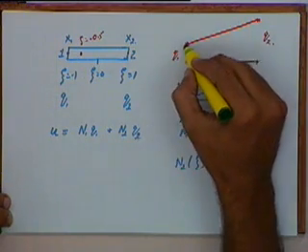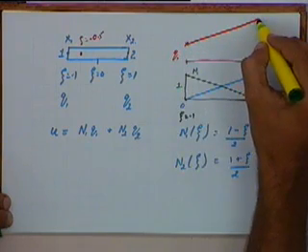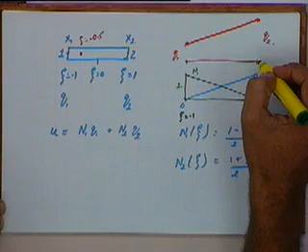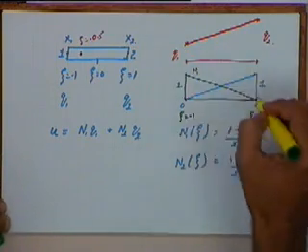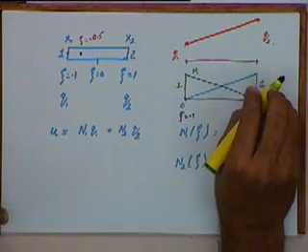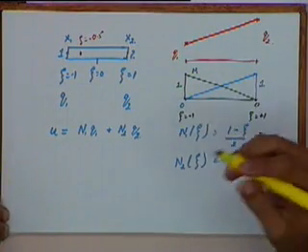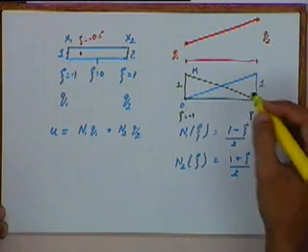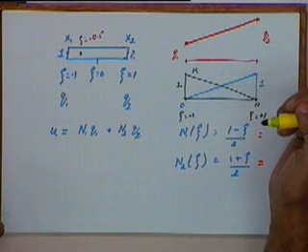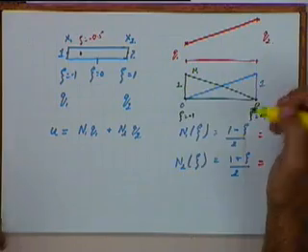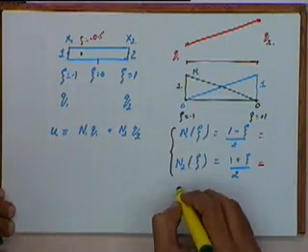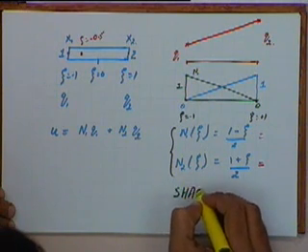Okay, and u is varying linearly from q1 to q2 along the length of the element. For a one dimensional problem at the moment it is very straightforward, but the same principle will also be used for more complicated 2 dimensional and 3 dimensional problems. So we will be extending the same principle later on. These expressions n1 and n2 are referred to as shape functions.